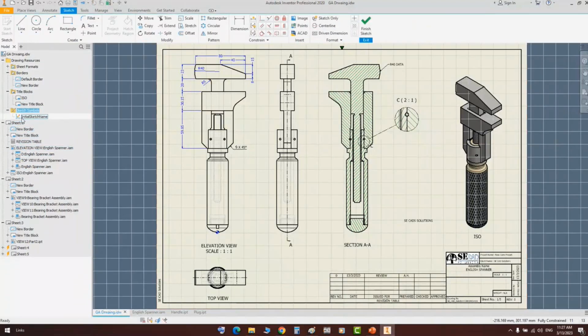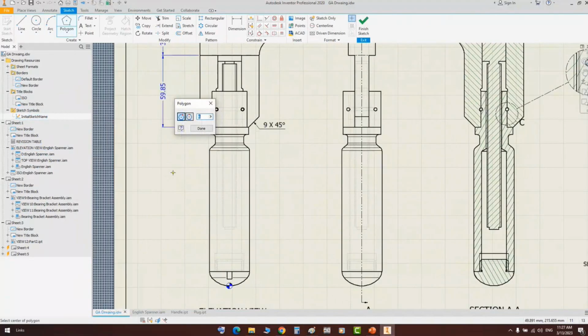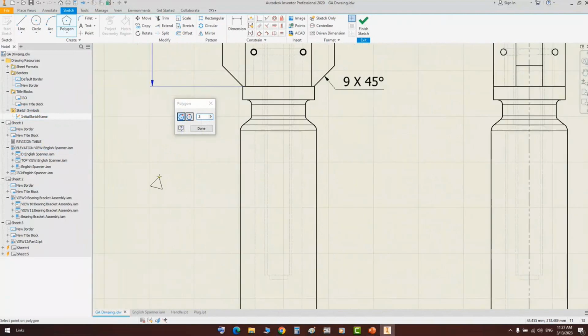Now we are on the level of detail of the sketch sample. Now let's create two rectangles. So from here, let's add a rectangle. So here we have this one. Let's add another one like that. And let's connect those points, make those lines parallel, okay, and make both of them in a horizontal level.